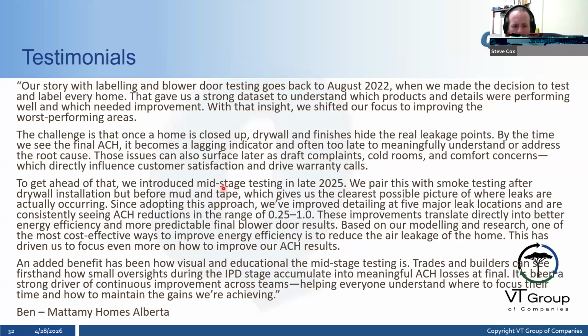Ben goes on to note how drywall and finishes can hide air leakage points, and that helps you find the justification for doing a mid-construction blower door test, because final ACHs are a lagging indicator of the root causes of the issues. I know Ben also reached out to me to acquire his own blower door system, and that's what they did. So they've started doing mid-construction blower door testing on their own.